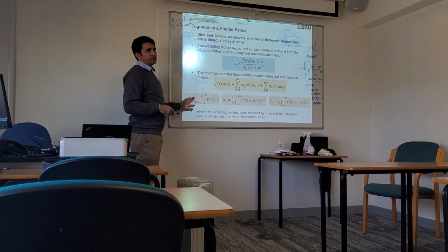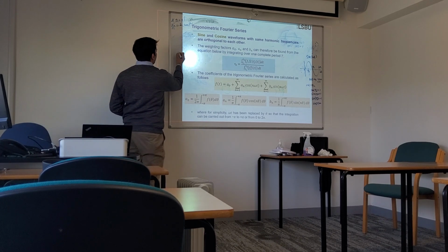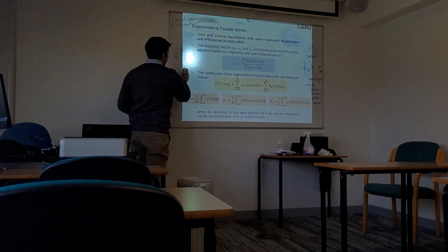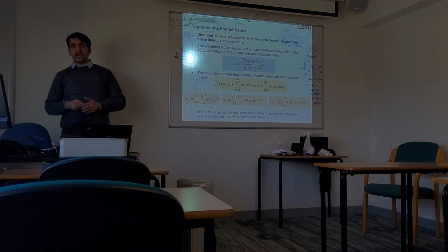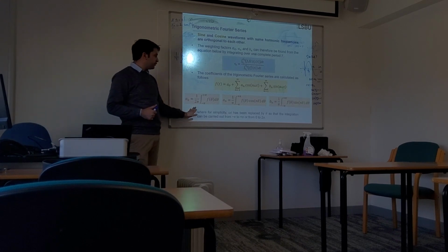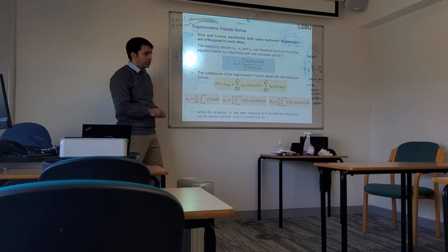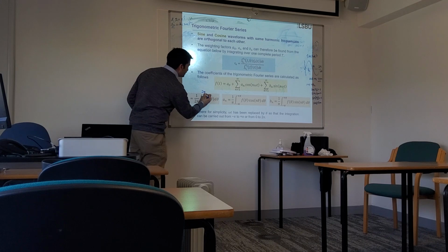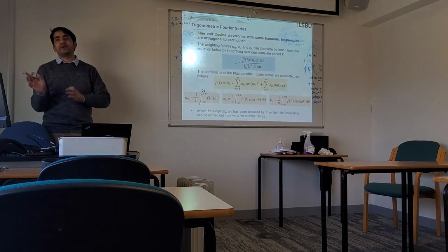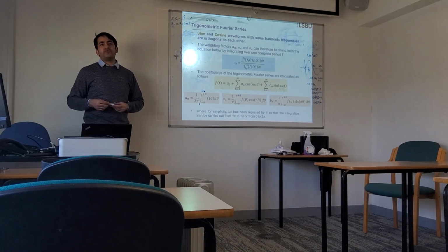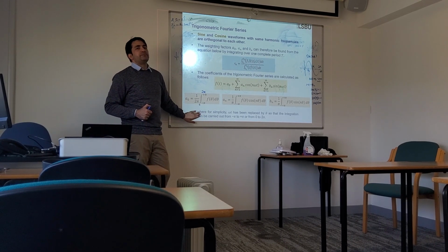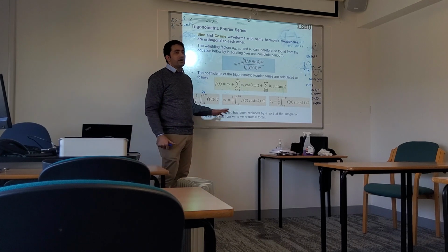So that's why in these equations, normally for average, we know that if you want to find the average, we say 1 by T, integral from time 0 to T, x of t dt. But here, since we have sines and cosines involved, we will limit our time period to 2 pi. That's why we have written 1 by 2 pi, integral from minus pi to pi, or we can say 0 to 2 pi. Either way is fine. You will see your function and then you can decide whether you need to take the limit from minus pi to pi or 0 to 2 pi. Both are fine, because the signal is periodic, f of theta. This was very simple, because it was a simple mean. However, a naught is slightly different.